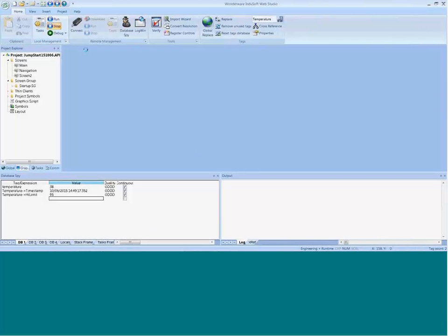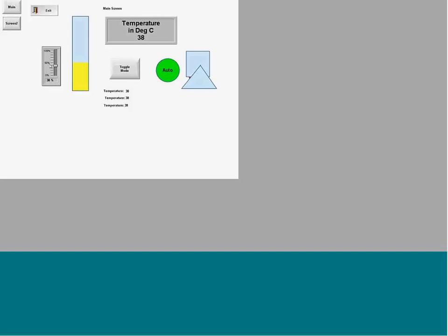So let's stop that and run that again. And now I should be able to set a limit of 75 as the limit. And now when I cross that 75 threshold, let's go up here really slow, 69, 75, then I get that alarm at the 75 limit.